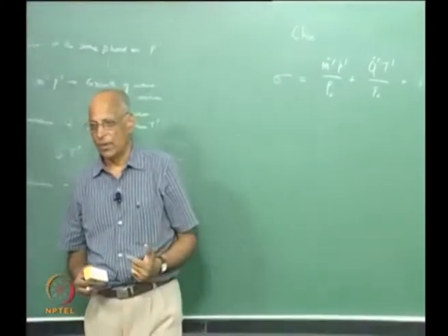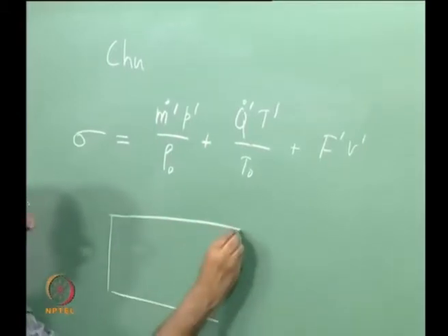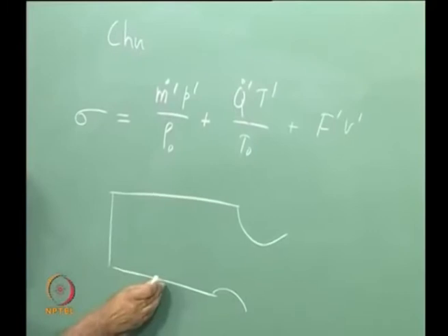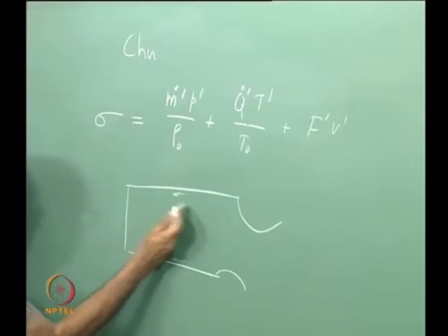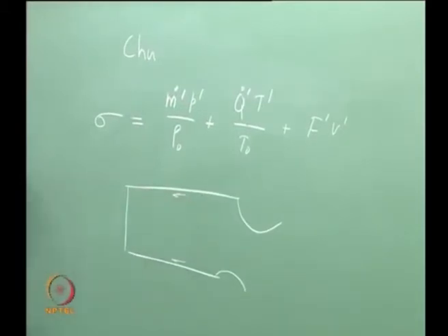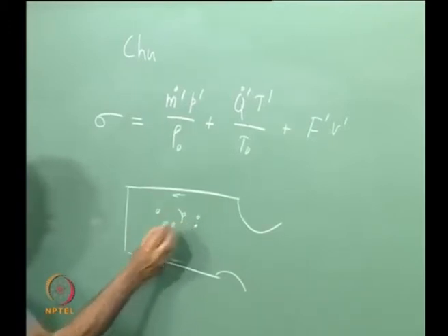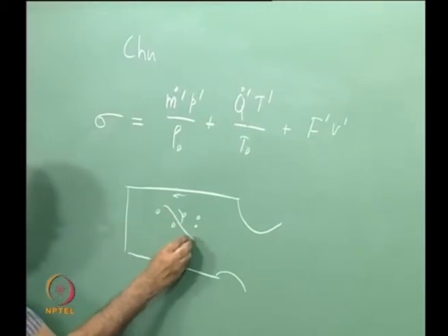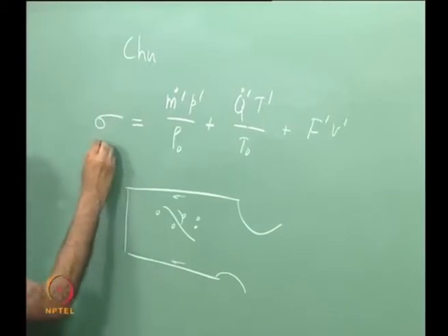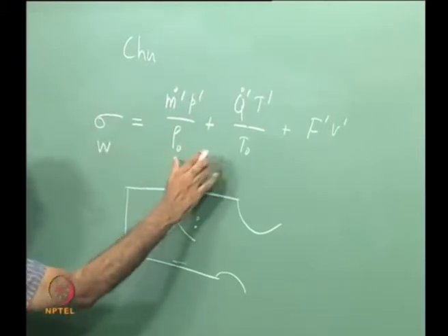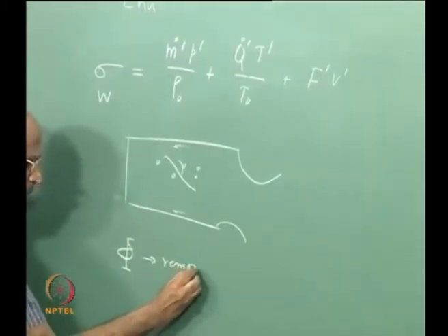Therefore all these three parameters are important. But in a rocket chamber again, we also have boundary layer, this point was made earlier, it could cause viscous drag, a wave when it is travelling gets retarded by the boundary layer. Maybe if I have solid propellants, I have particulates, particulates will cause drag, it will break up the wave. When a flow turns it loses energy, and therefore there are also some factors. Just like I have sigma watts adding energy, I could also think in terms of some capital phi which removes energy from the wave.